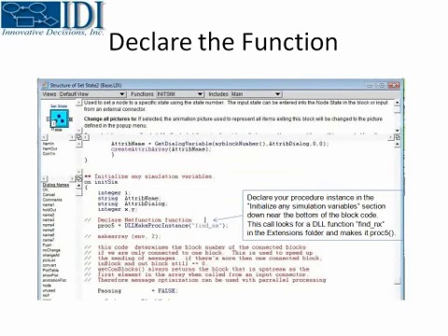The next thing that you'll want to do is go down to the bottom of the block, which is the area where you'll find the on-init-sim. This is the place within the block where you initialize all of your functions or variables at the very beginning of an ExtendSim program. So this is the place where you want to insert your code, where you initialize your call function. In my particular case, remember proc5 was the procedure that I was going to use.